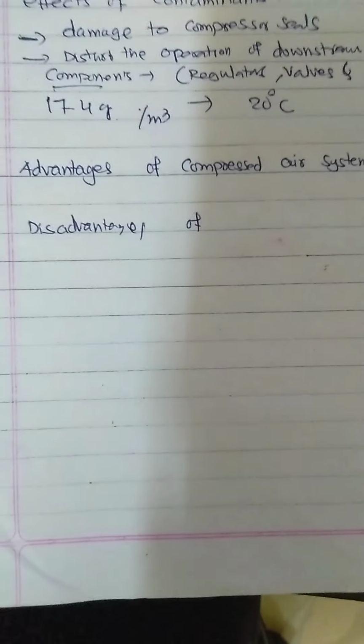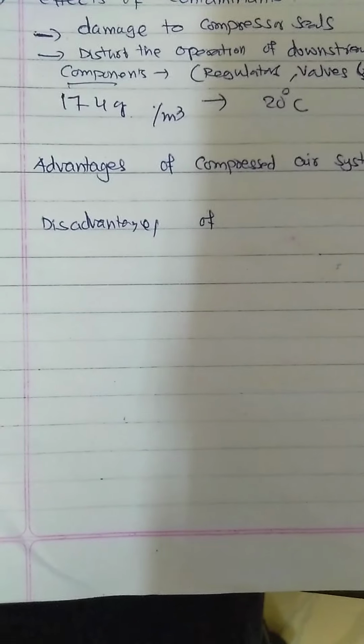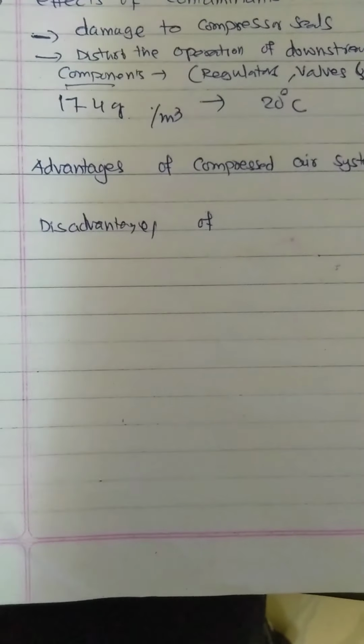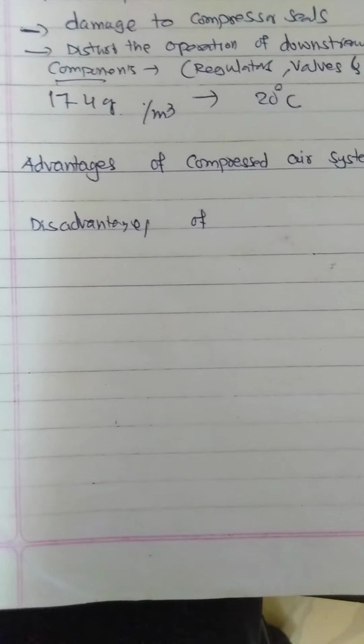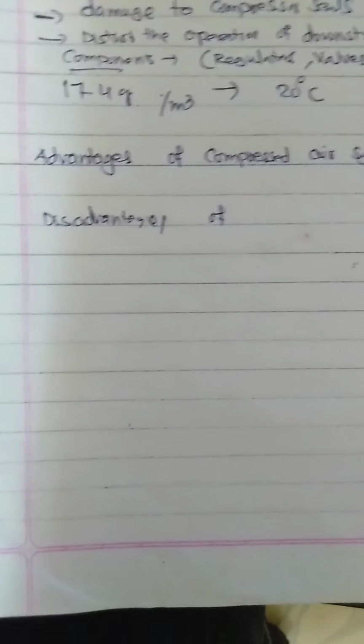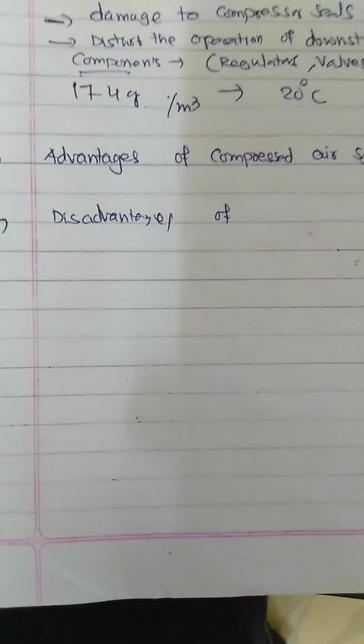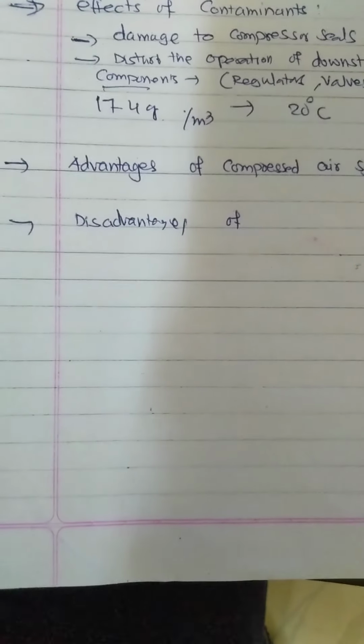Then comes the cost. Compressed air is a relatively expensive energy medium. The high cost of energy is compensated by inexpensive components and high performance. Then exhaust air is noisy, it gives noise. Nowadays this problem has been solved with the availability of efficient silencers, or you can say mufflers.